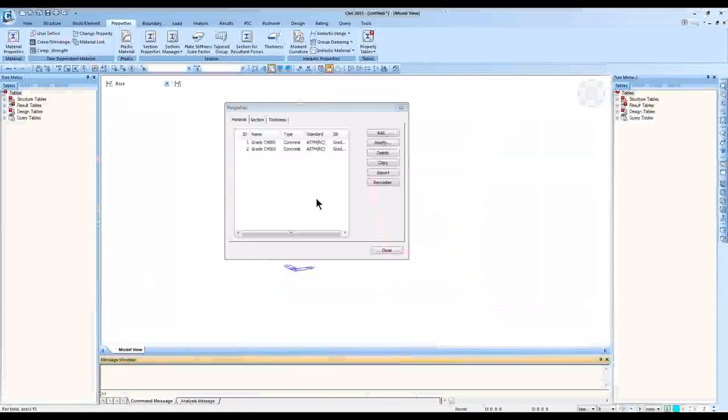And the reason why I input the material in Midas Civil again is because this material is something that the program is actually going to use for calculating the self-weight and also the basic material. So this isn't related to calculating different parts to the section. This is the actual base material that you will need to define.